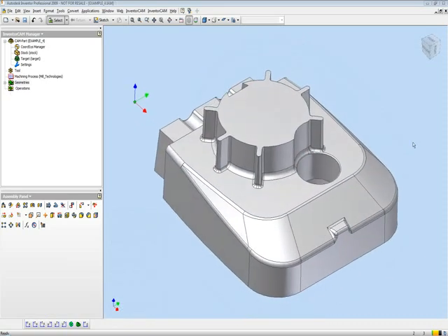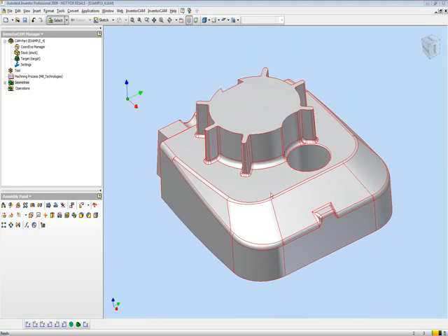Now, in this next part that I have on the screen, I'd like to actually machine these surfaces around here according to the shape of the upper surfaces and towards the shape of the lower surfaces. For that, I'll be using Morphed between surfaces. I prefer Morph between surfaces rather than Morph between curves in this particular case, because it's a lot easier for me to pick the surfaces around the part itself rather than picking each curve individually.